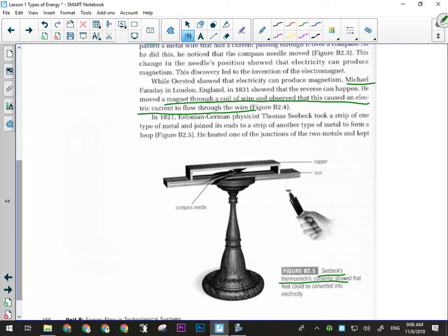So like I say, a few of the places where we would use that would be like in circuit breakers. In your house, how many people have seen the electrical panel in their house? If you run too much electricity through the panel, then the breaker will pop, right? Everything that's connected to that circuit then goes off. The way that works is essentially it detects if there's heat building up in the circuit, and heat builds up in a circuit if you're drawing too much power through it. So if this circuit gets too hot, enough of a current is formed that we can use a small thing to pop the circuit open.